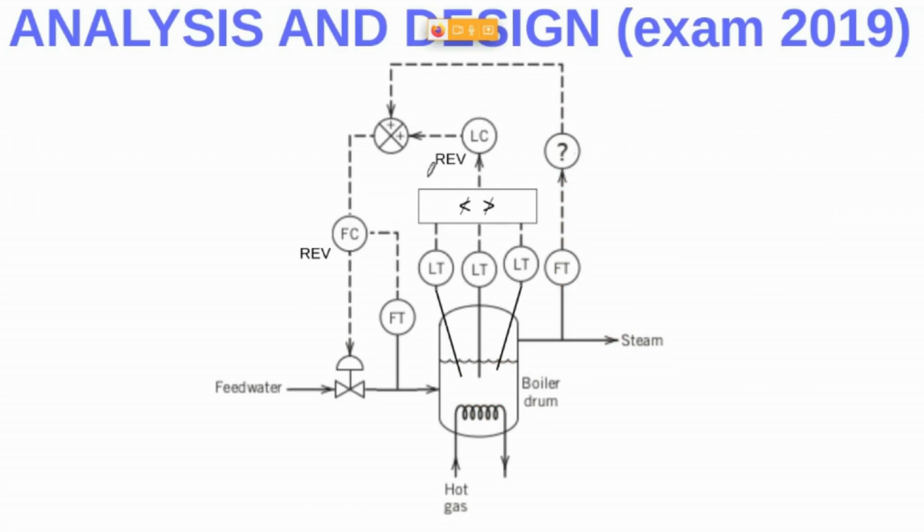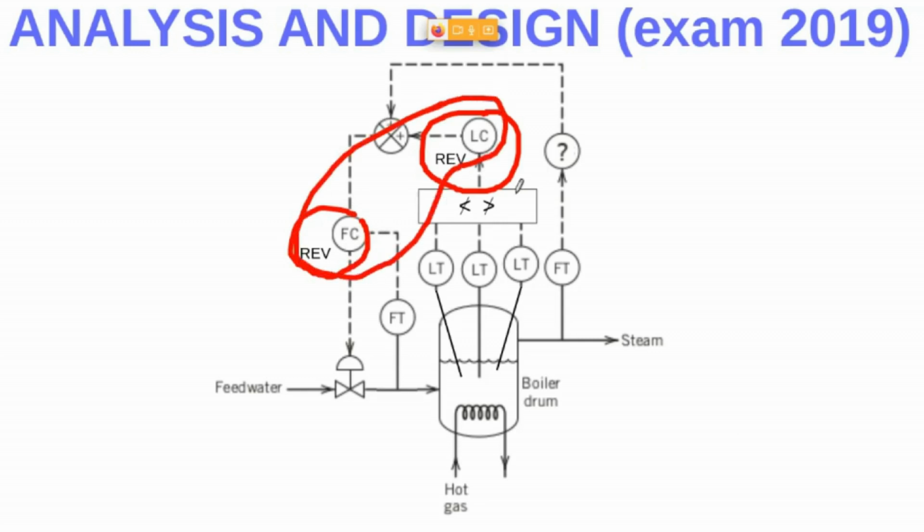Here you have my design more clearly, right? As you can see, the selector, not the lowest nor the highest, and the 2 additional level transmitters. This obviously will be configured in a reverse action, as I told you before, and the same goes for this. And as you can see here, we have the cascade, we have the selection controller strategy, and additionally, we have the feed-forward controller.